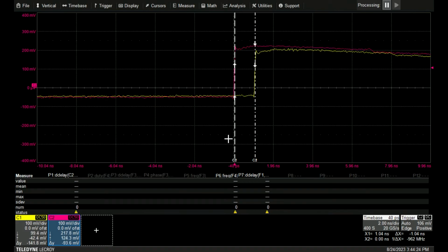Here we have put the component in ramp mode. We can see on the LabMaster that the two ramps do not start at the same time. We have measured the delay. Using this development GUI, I have access to the TX delay registers of the FPGA, and I can modify the delay value of the sent samples in the FPGA. I will change the TX delay value on the GUI.